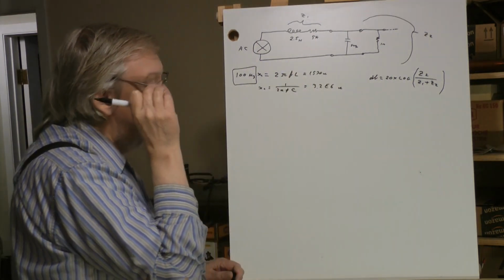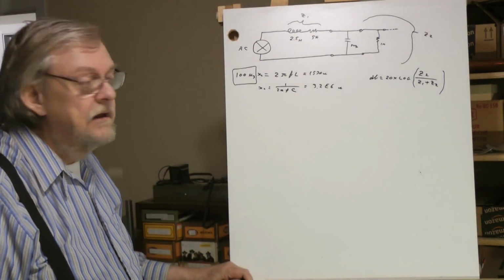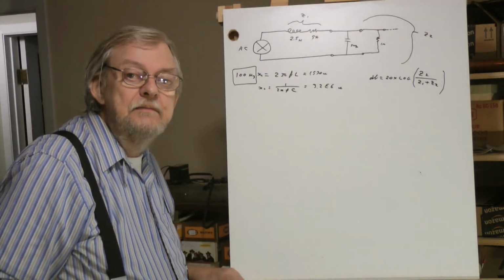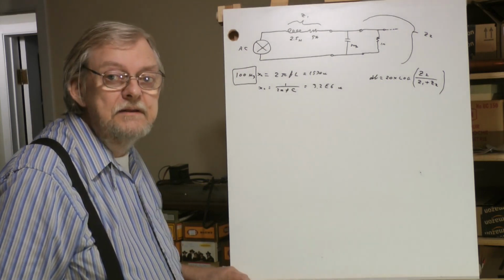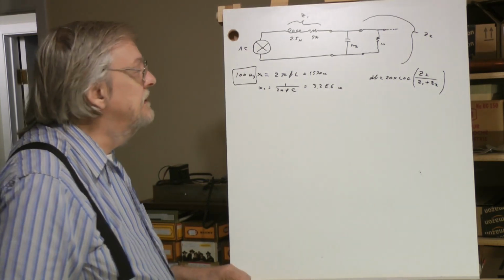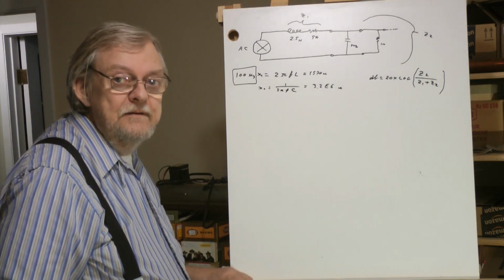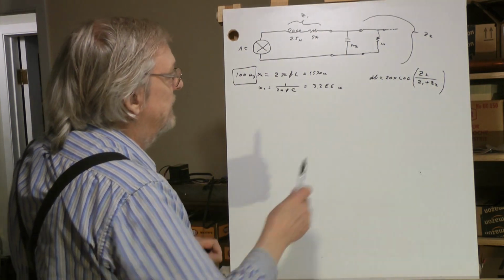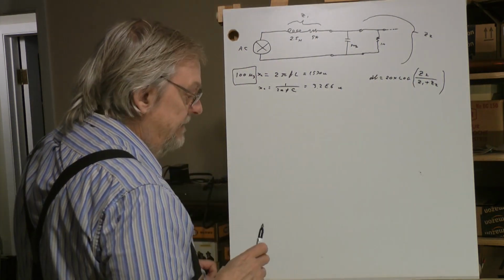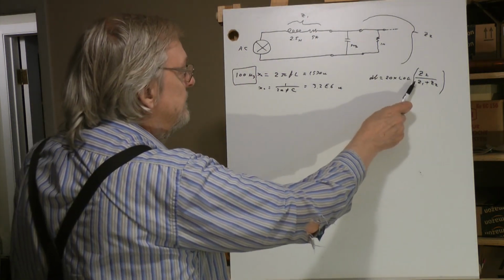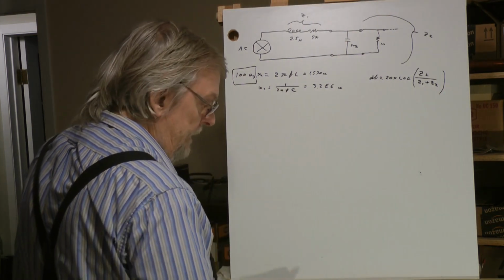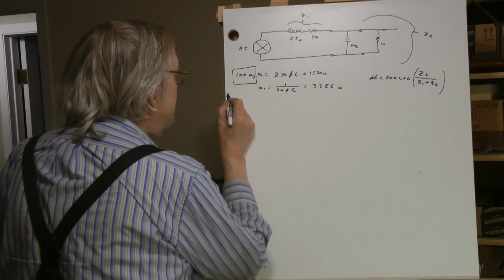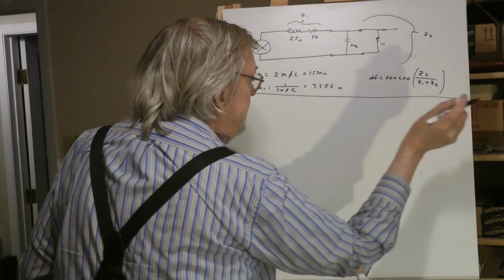So most guitar amps have a filter to increase high frequencies. Now a humbucker has maybe 7 henries, maybe more, so that's why humbuckers sound so much darker, bassier, because they kill the high frequencies more. But we'll see that on the graph. What we've got to do now is come up with the math. We need to figure out Z1, Z2. And again, I've pre-done stuff here so I don't have to waste time with a calculator.